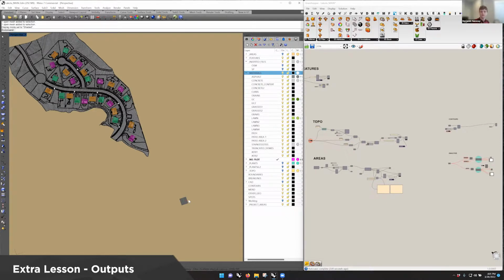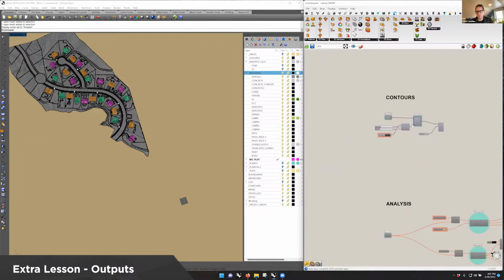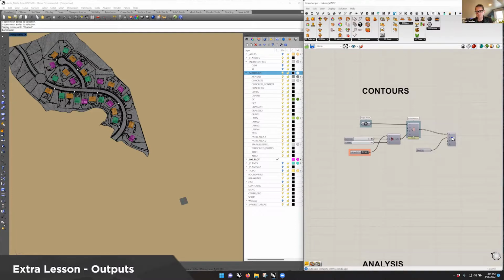That's the origin point of Rhino, and things that are close to the origin don't have to do as much rounding. So if someone takes a survey and it's related to that origin in space, it's good to remember to bring that survey and that geometry, either copy it and bring it closer to the origin, or just move it closer to the origin so that Grasshopper doesn't start breaking, which we've run into a few times when you're trying to process things. Yeah, Rhino will have trouble previewing things, and sometimes stuff will break with some of the things that we're doing in Grasshopper.